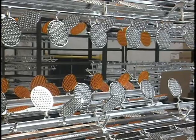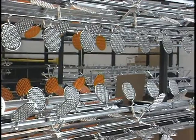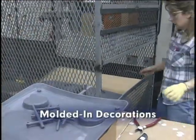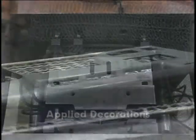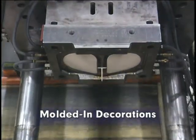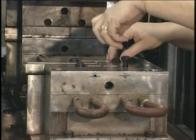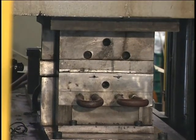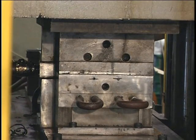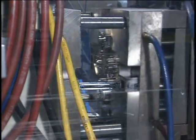Virtually all plastic products require some decoration. The methods of decorating molded parts include molded-in decorations and applied decorations. Molded-in decorations are those machined into the mold, such as textures, or by implant, as with two-shot molding, where an insert is placed into a mold and then molten plastic is injected around the exposed areas of the insert, creating the part. Even pre-colored plastic resins are considered molded in color.